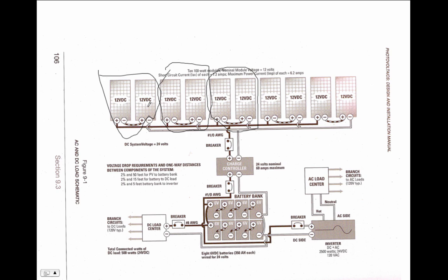7.2 amps. Maximum power is 5.2. So 5 times 5, about 25 amps will be coming into this charge controller. So we'd have to have a charge controller that's big enough to handle 25 amps.